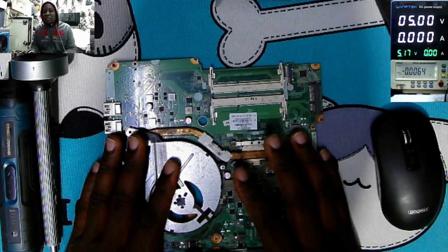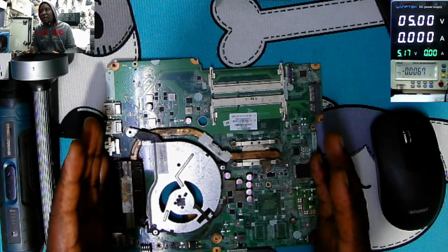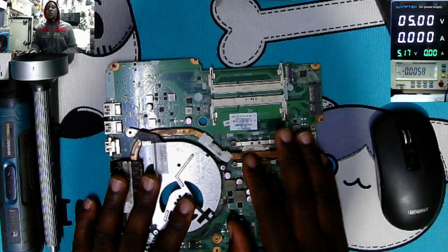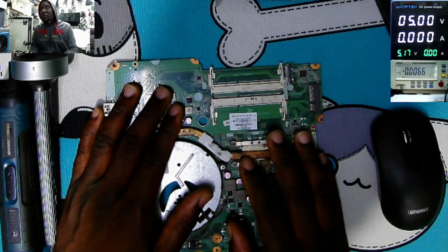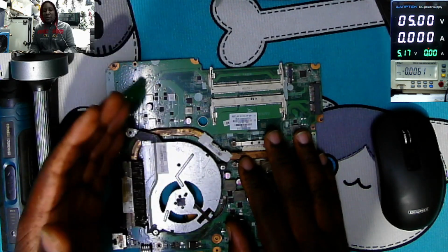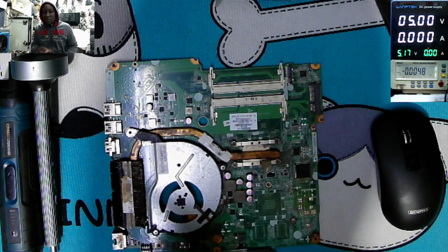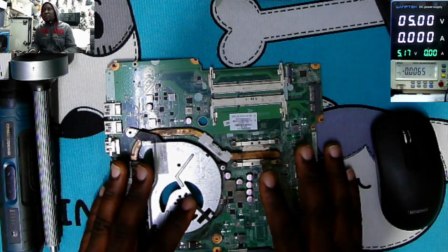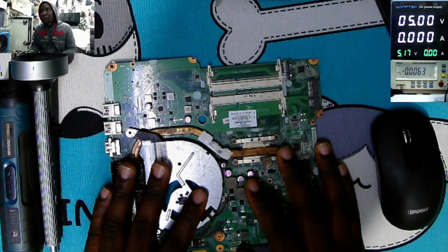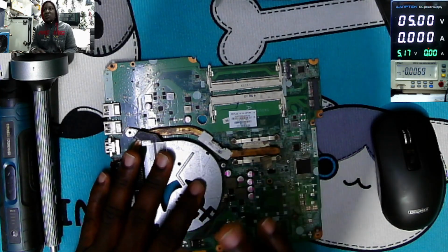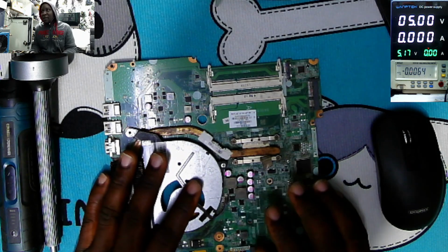Even with the lower voltage, you can use a thermal camera, if you have one. If you don't have one, you can come with some liquid, like alcohol, and see which component is drying quickly. We have done this so many times. If you check some videos, we've done this so many times on finding short circuits.